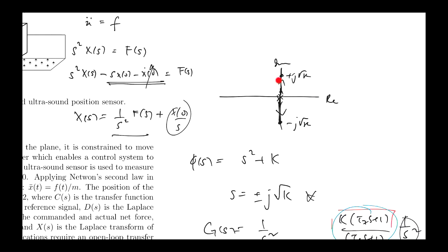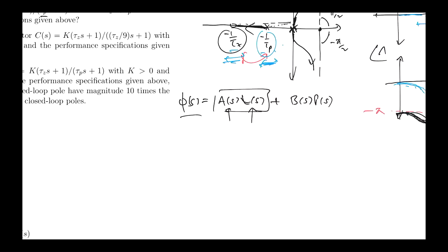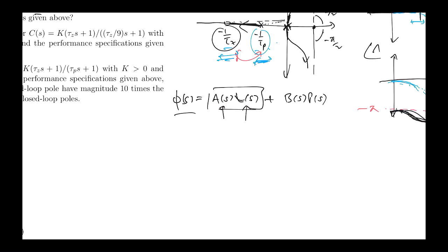It's pushed these asymptotes here, along which the root locus approaches the zeros at infinity, and the lag compensator here has pushed them into the right half plane, causing closed loop instability. A lead compensator does the other thing, right? So with the lead compensator, the 0 of the compensator is closer to the imaginary axis than the pole.